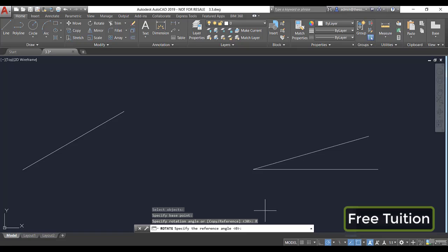So I'll select reference angle, and you already know that this angle is 16 degrees. So type 16 for reference and enter. And now AutoCAD will move 16 degrees back. And if it moves 16 degrees back, it will end up with this horizontal line. So that means the measurement will now start from this horizontal line because we have added 16 degrees as a reference angle. So now if you type 90, you'll end up with a perfectly vertical line because we have already added our reference value, which was 16. So AutoCAD will just take that line 16 degrees back, and then it will start measurement.